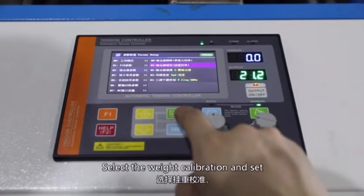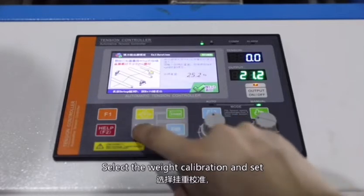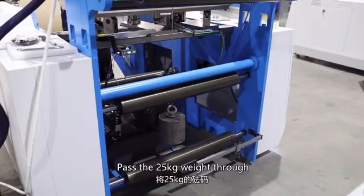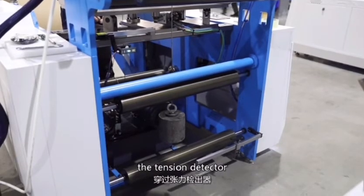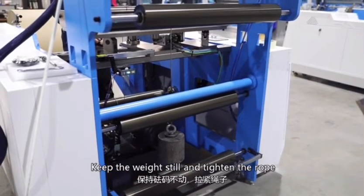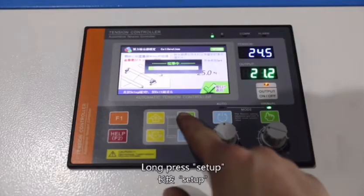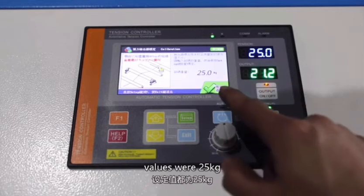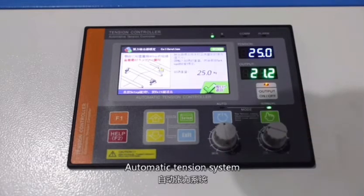Select the weight calibration and set the weight at 25 kilograms. Pass the 25 kilogram weight through the tension detector. Keep the weight still and tighten the rope. Long press Setup. Both the detected and set values were 25 kilograms. Automatic tension system setting is complete.